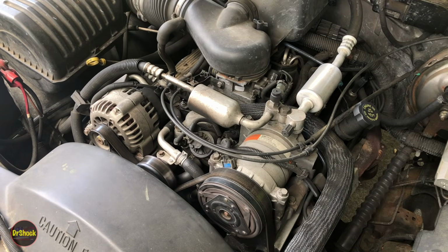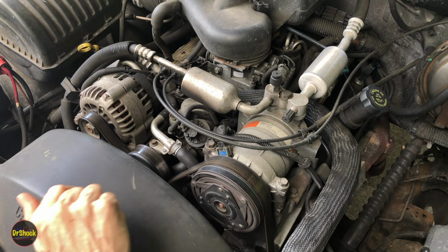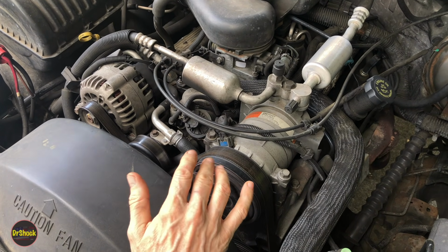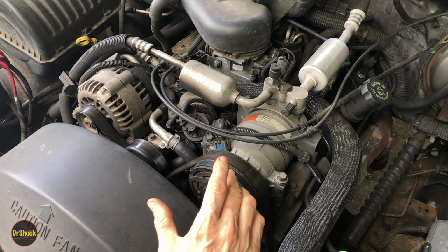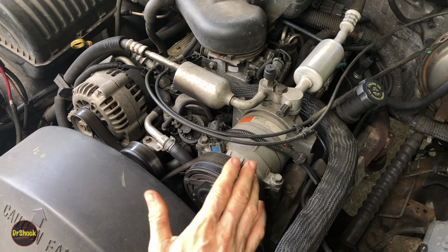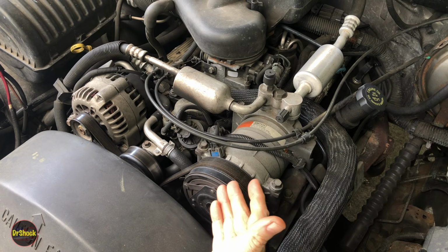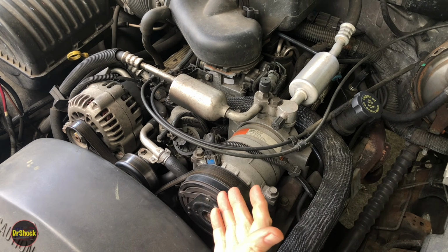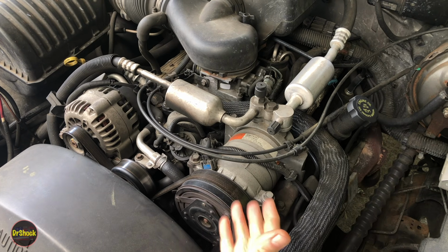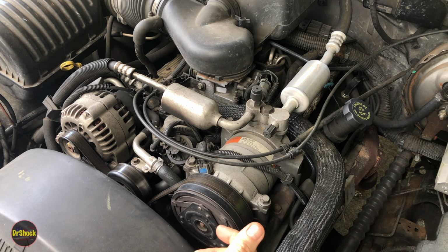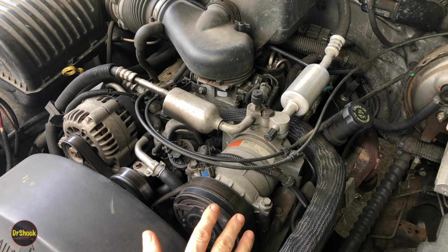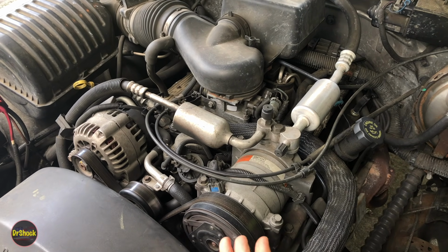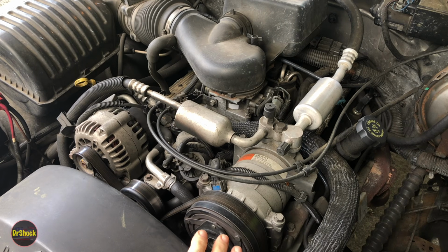Alright guys, in today's video we're going to be diagnosing an intermittent air conditioning problem. What we've got here on this 98 Chevrolet K2500 is a situation where intermittently the compressor will cut off. It only happens when it's very hot outside, and after the driver has been driving for 30-40 minutes or so, then you'll get these intermittent cutouts of about 5 to 10 minutes each, and then the AC will come back on again for some period of time, and that'll repeat until everything cools down.